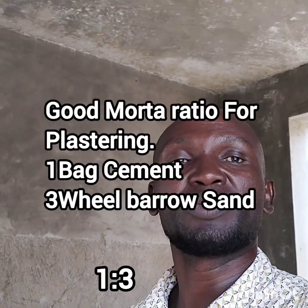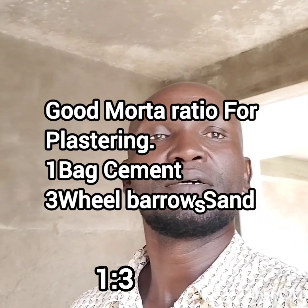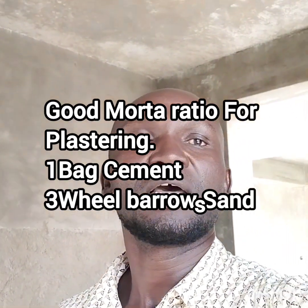Then once you've done that, you also need to use a proper ratio. We like using 1 bag of cement to 4 wheelbarrows of sand, but because of so many impurities in the sand, and sometimes you're not sure of the quality, use a ratio of 1 to 3. 1 bag of cement and 3 wheelbarrows of sand. That one will guarantee you good workmanship.